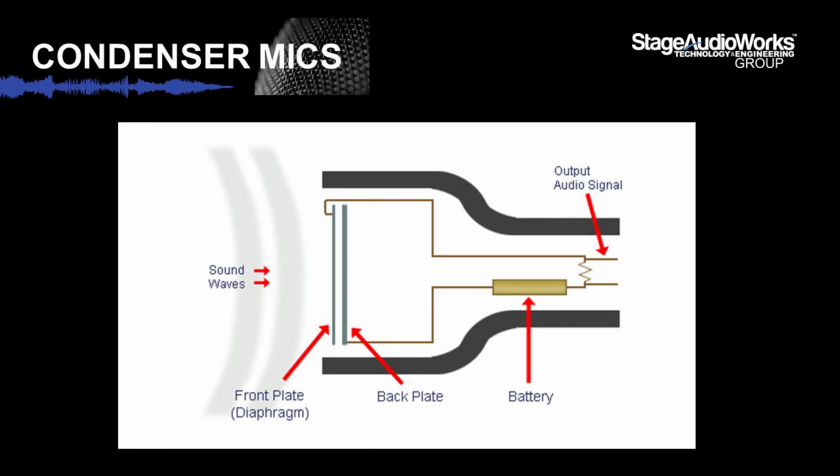When the plates are close together, capacitance increases and a charge occurs. When they are further apart, capacitance decreases and a discharge current occurs. A voltage is required across the capacitor for this to work, and that's why we use phantom power typically, but in some mics you can use a battery as well, but we don't see that many of those today.